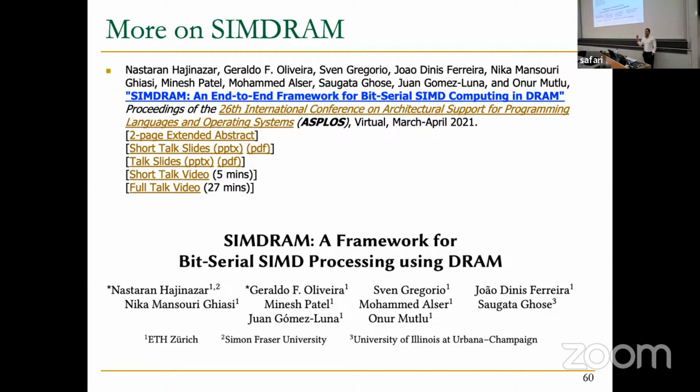So this BBOP instruction is treated as any other load instruction. So it's registered in the MSHR entry, goes to the memory hierarchy, and eventually needs to go back to the CPU as well. So if the CPU is going to depend on that particular BBOP instruction, it's as if it's depending on a load. So it's waiting for it to move back, basically. So in that sense, this is not asynchronous to the CPU.